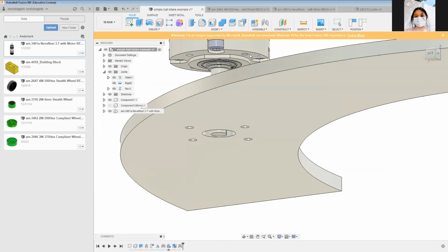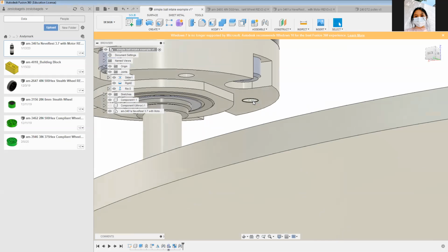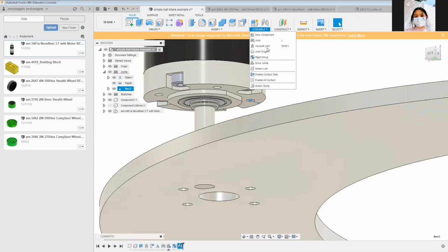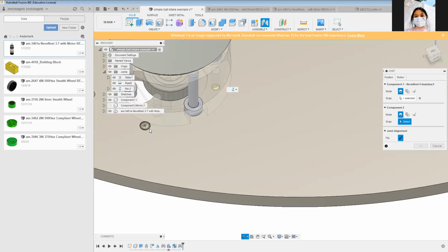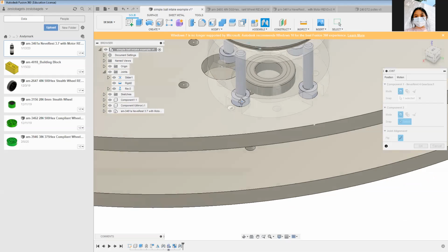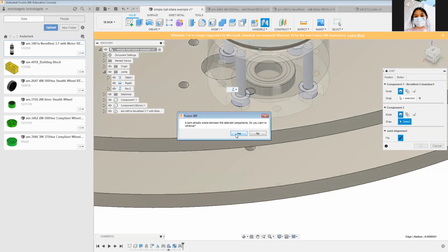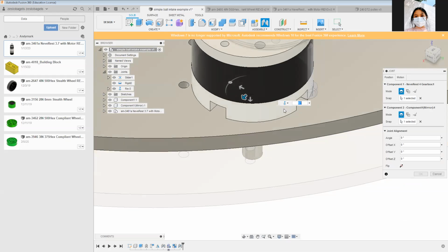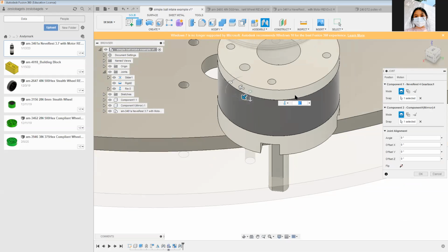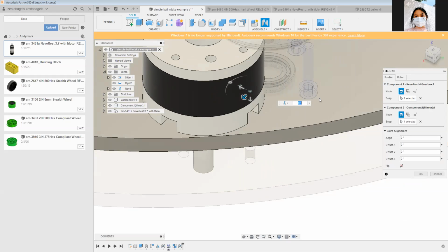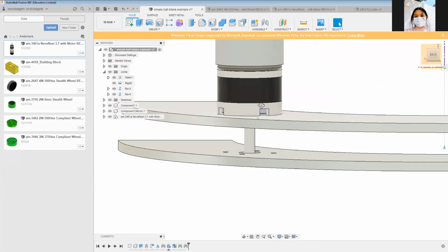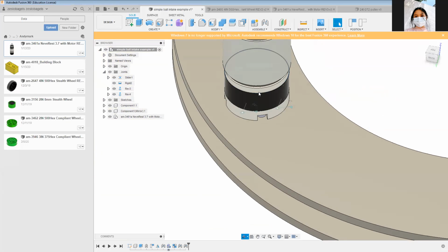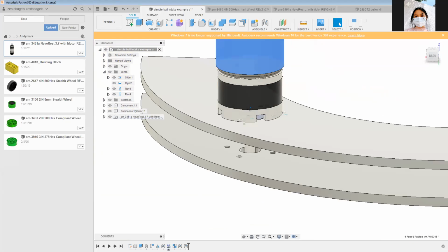okay, I'm going to revert position so I can, okay. So I see there's a joint there, and I want to put a joint in the second hole. It's going to be on this hole, so I'm going to reveal this thing so I can see. I'm going to say it's right here. And there's already a joint between these components. So that means if the distance between those holes is not exactly the same, then there will be an error popping up. But hopefully there will not be an error. See, okay, so they're exactly the same. And now this motor is essentially just rigid, like screwed in.